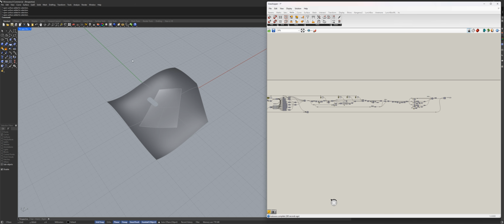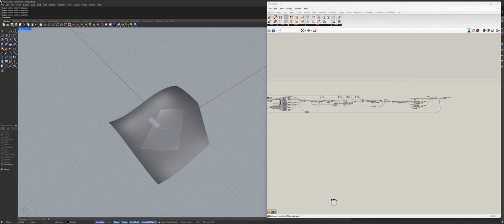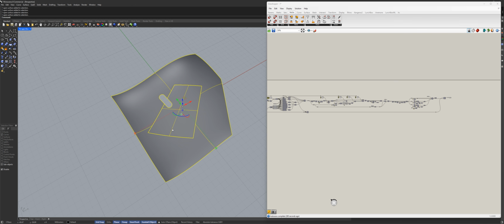important later, onto our BREP, basically bypassing the fact that we can't rely on the parametric space of every individual object of our collection. But for that, we need first a surface which approximates the geometry which we want to get a pattern on, and second, we need to convert these collections of surfaces into somewhat of a uniform geometric type of data, which actually has a name, it's called Polysurface or a BREP.